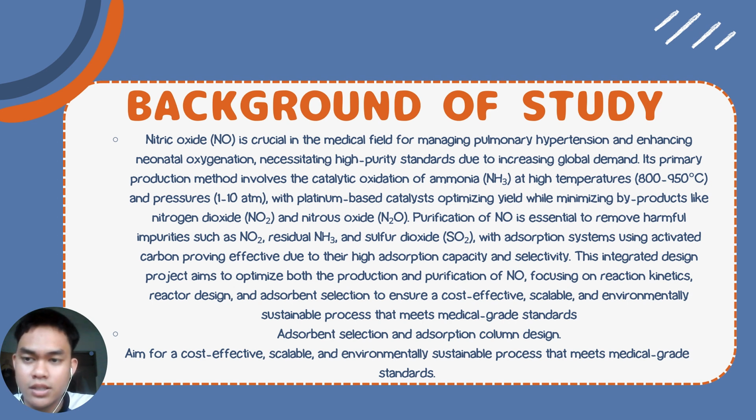For the production analysis, we have investigated catalytic oxidation of ammonia with excess oxygen. To establish this optimal condition, we have prepared the temperature around 800 to 950 degrees Celsius in a controlled pressure setting, and we utilize a platinum rhodium catalyst to enhance the reaction rate and selectivity.